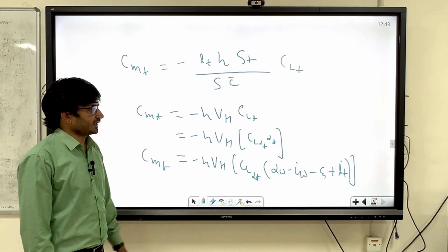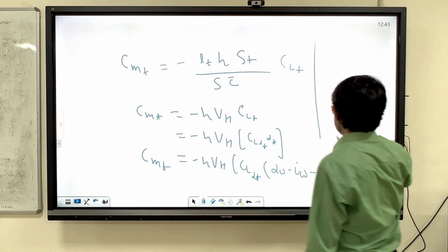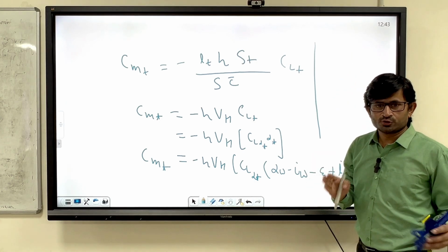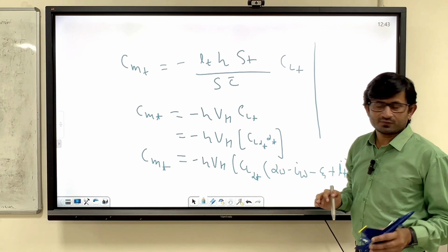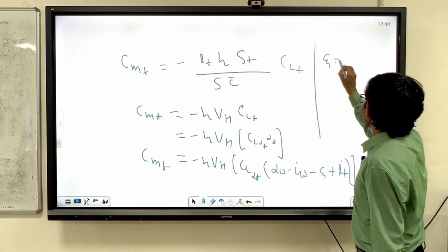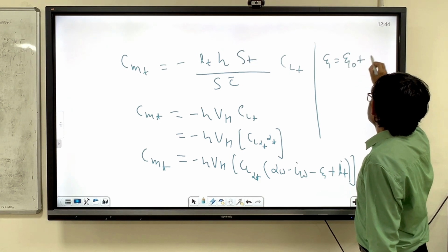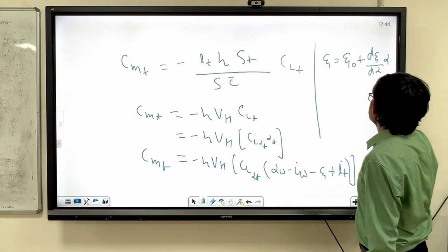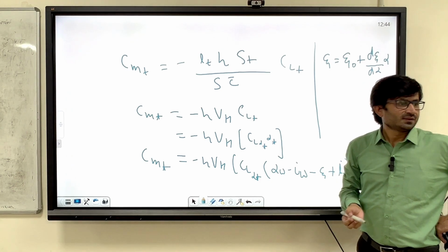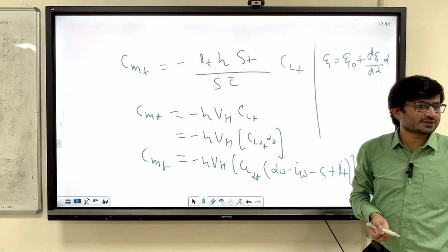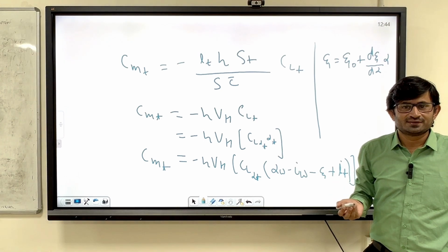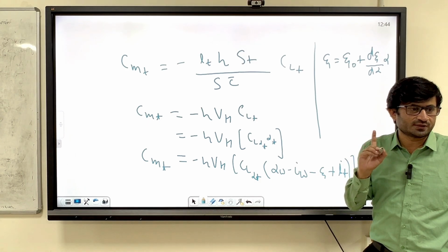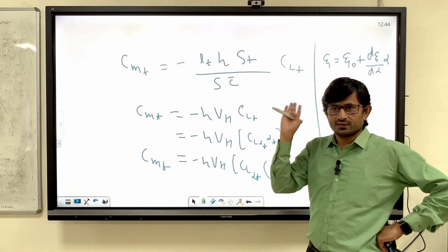Now you defined epsilon, here epsilon naught. What is epsilon naught? It is the downwash angle. So you may further write, it is simple to model using Taylor series, right? Taylor series is nothing but what? First order Taylor series you can expand: dou epsilon by dou alpha into alpha. Simple. You can say CL equal to CL naught plus CL alpha into alpha, which also comes from the Taylor series. Cm equal to Cm naught plus Cm alpha into alpha, also from the Taylor series. If you take just first order, you neglect the higher order terms.